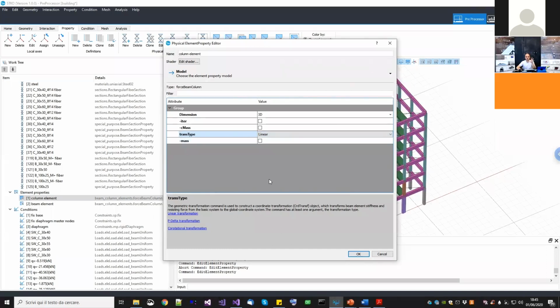So we will start with just a basic frame model. Everything is continuous with just material nonlinearity. Then in a second stage, we will add the P delta effect so that you can see, for each component, what effect it has on the response. Okay, so we start with the linear kinematics.